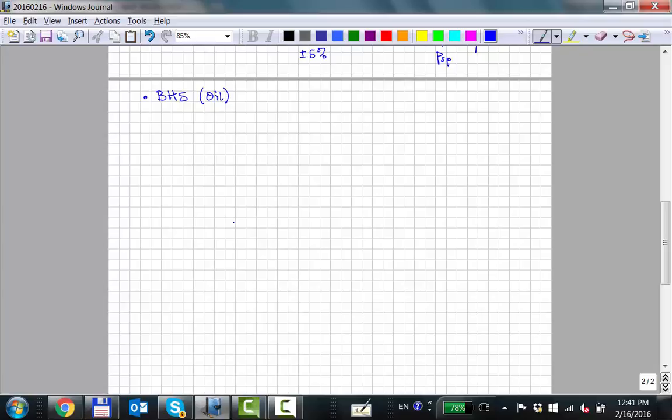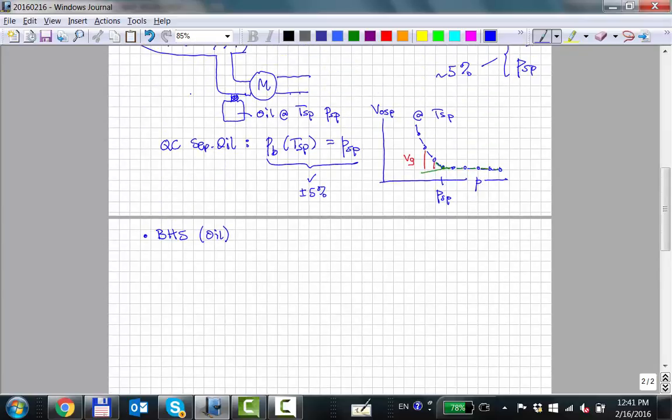So I don't really know what they're doing out in the field. But what they used to do with these traditional bottom hole samples of oils is that in the field they would actually make a similar test to this pressure volume test and look for a discontinuity. They would try to measure in the field a bubble point pressure. Not at reservoir temperature, because you're at the surface.